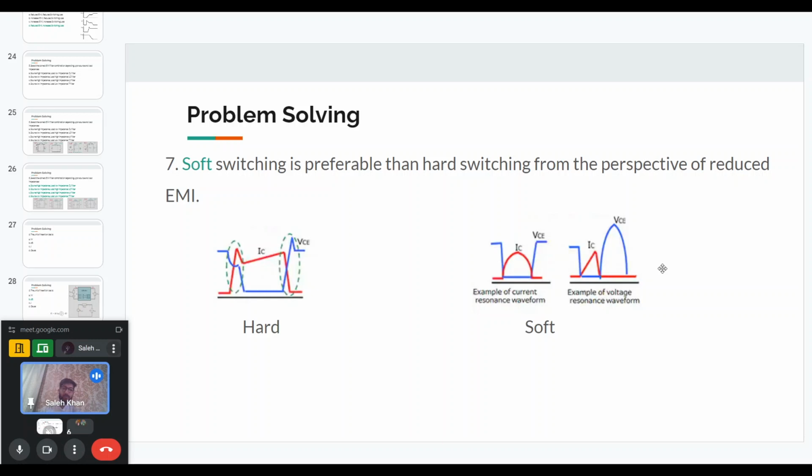There are other types of soft switching as well. For example, in the buck converter we have the inductor current that rises and then it falls. But if we have a situation where it falls very close to zero, or actually to zero, it may be a DCM situation. In that case also, because the current actually goes to zero, it may lead to soft switching, and then again di/dt will be limited because the switching is happening at a very low current.